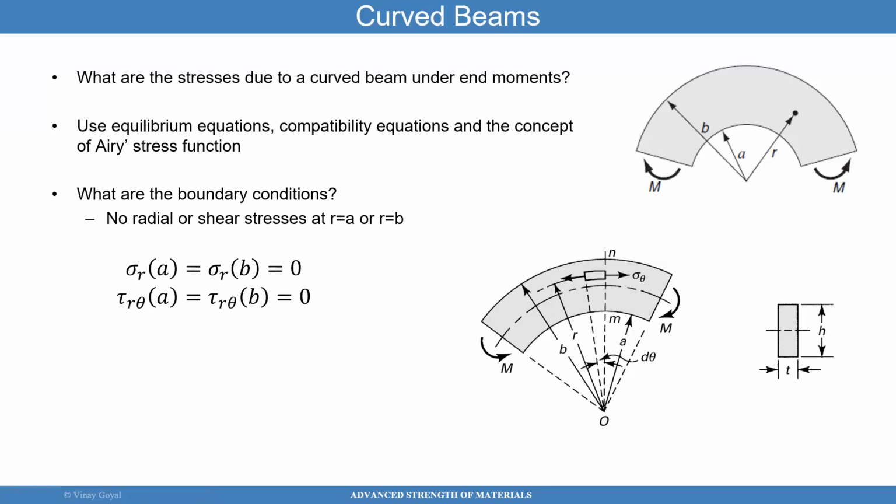So let's look at, I'm going to just do one example on one surface, and then you guys can figure out the other surfaces. So let's look at the surface at R equals B. So R equals B, that surface is this one here. That's the surface we're talking about. If I were to look at what's going on on that surface, we have a radial stress there, potentially, sigma RR. And then you have a tangential shear stress, sigma R theta.